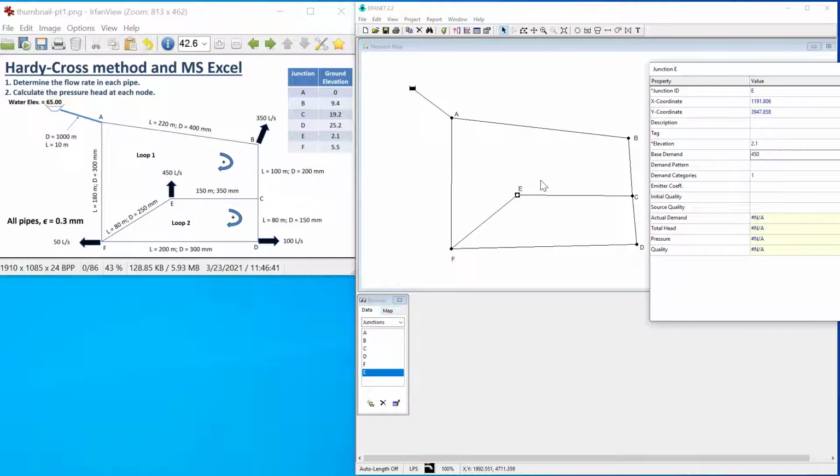So we have defined where the outflows are and how much, and the system will automatically draw that flow from the reservoir. So I don't have to tell it how much should come out of the reservoir, because it will apply continuity to calculate the outflow through this pipe required to feed all of those locations in the network. Okay, so I've defined all the data that's needed for the junctions.